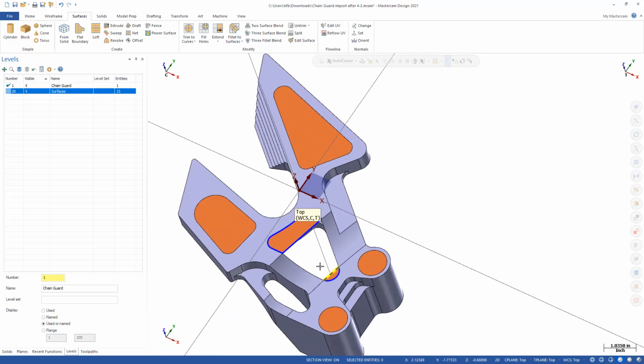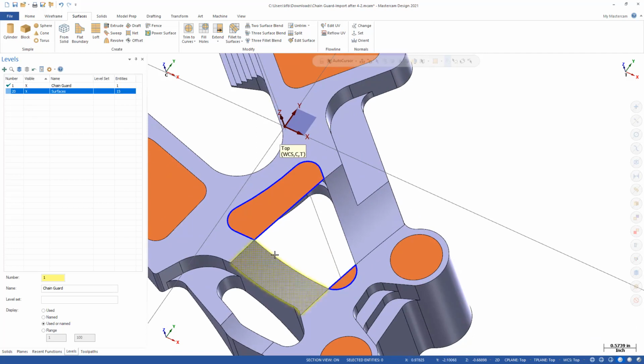So finally, let's focus on this inside area here. And there's a bunch of different ways of creating this geometry. We're going to focus on one here, but you could use a loft. You could use a net surface. There are some different options that you could explore. I'm going to choose the net option. So the net option needs 4 pieces of geometry.